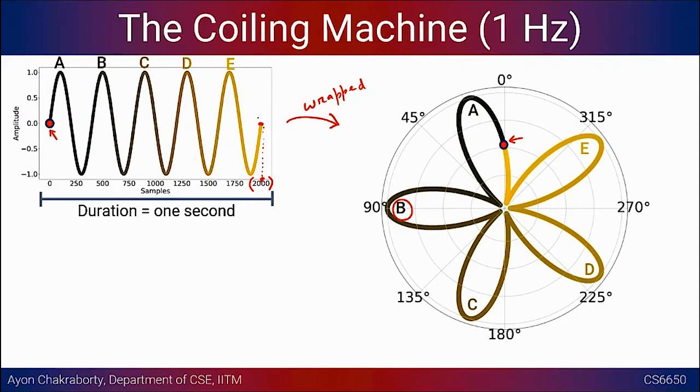And then if this is F, so this portion is F, that comes back to 2 pi. And I have made it 1 hertz, right? So the rotation speed is 1 rotation across the circle with data worth of 1 second. So for now, we will just restrict ourselves to 1 second worth of data only. Later, we will see how to deal with sample rate and so on. But currently, we are just sticking to the fact that all the input data we have is in terms of 1 second. Okay, and this has k number of samples, so k is your sample rate.